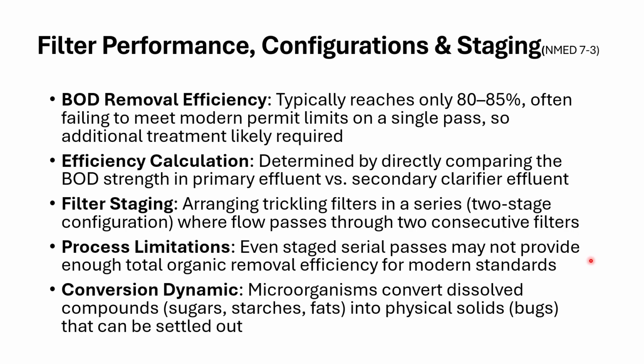Okay. There are some limitations though. For our modern NPDES permits, even if you do this a couple of times, you're still not going to get down to the levels that the regulators wrote into their permit. And that's understandable. But you are knocking a whole heck of a lot of the organic load out of the influent and effluent at a very low cost, a very efficient one.